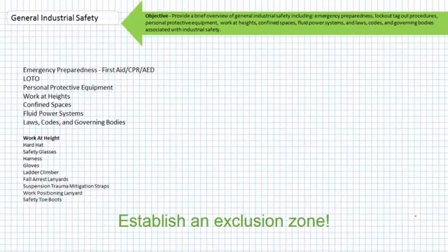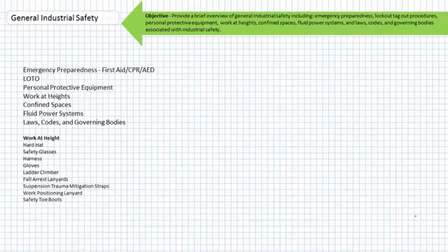A final note about work-at-height scenarios is to be aware. Be aware of things above you. Never walk under a suspended load or stand below people working. Be aware of people working below you. Always tether tools to you. This sounds stupid, but I'm serious. Be aware of bees. If there's one thing bees love more than stinging you, it is stinging you while you plummet to your death.